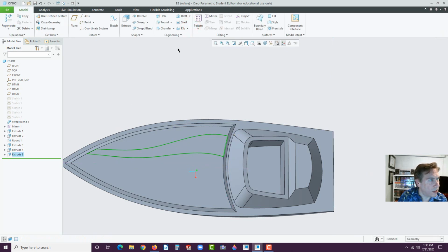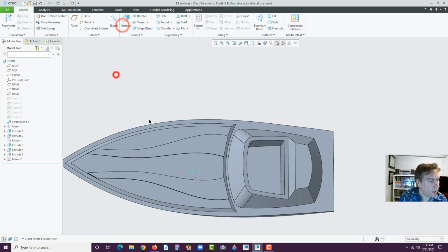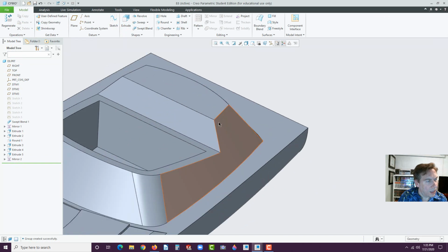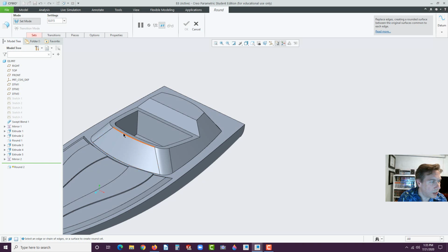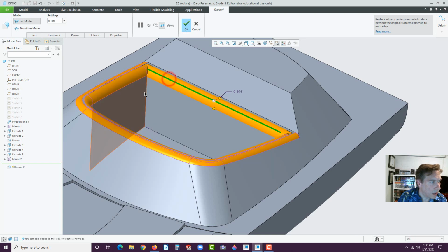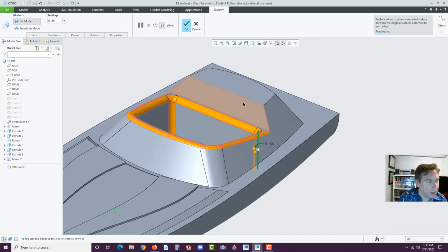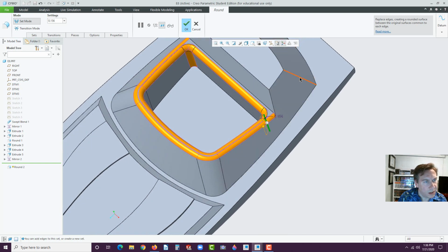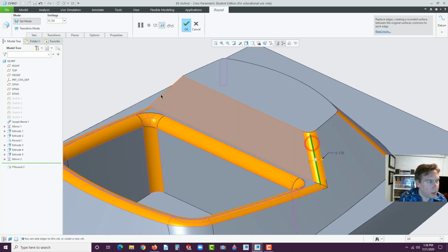Hit OK. While that's selected, we go to mirror, select the right plane. There it is. Now, any additional features here, it's just rounds and it's just tinkering, trying to get in the geometry that you think looks best. Put a lot of padding in here. All right. And then we could put in some additional fillets here and here. And if you want, put them in here and here too.